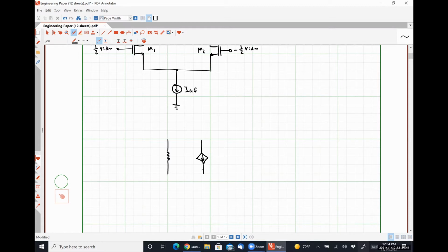And so these two guys right here represent transistor M3. And we will no longer be neglecting channel length modulation. So we will have some resistance Rout3 in parallel with a dependent current source that gives us gm3 VSG3 amount of current.